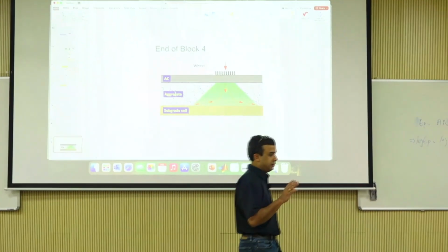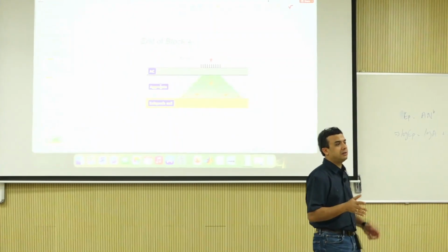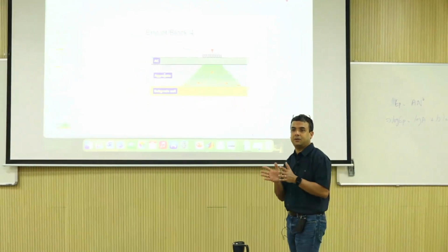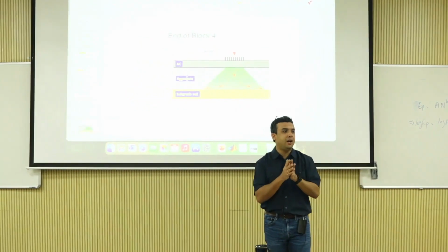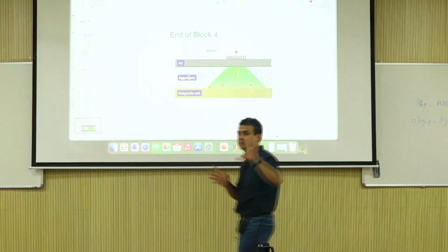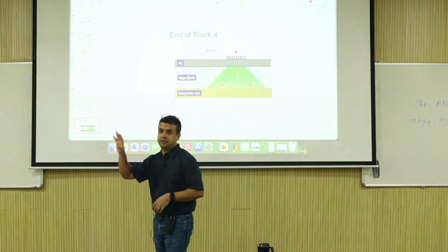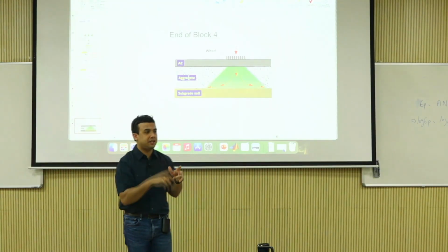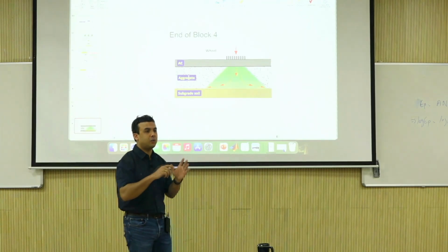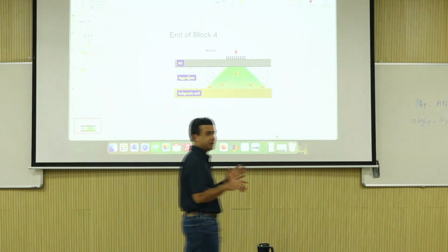So most important behavior is repeated loading behavior for aggregates, unbound materials, right? Because they are loaded under repeated loading. Resilient modulus and permanent deformation. One is kind of an elastic response after some initial settlement. The other one is that settlement part, right?